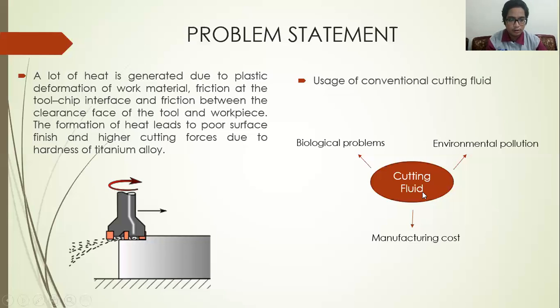These cutting fluid issues are three. First is the biological problem. This biological problem is related to the exposure to cutting fluids, which may be a cause of skin irritation and of skin cancer. The possibility also exists of a hazard to the lungs from the inhalation of fumes in the machine shops. Next is the manufacturing cost. This cost is related to the fluid purchase, storage, maintenance, and fluid disposal.